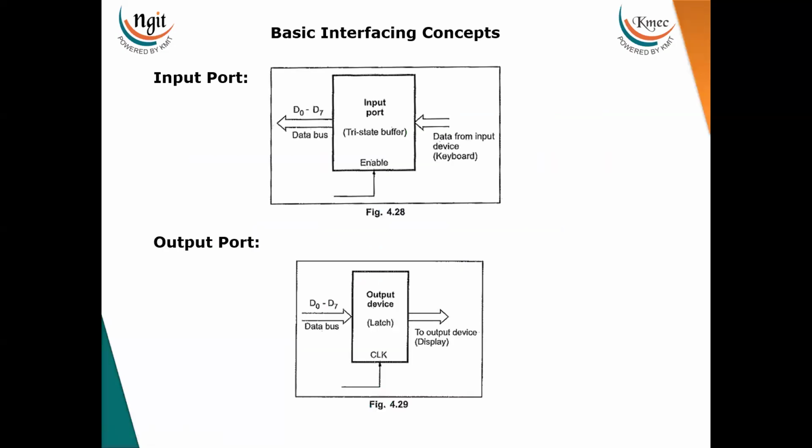In this lecture, we will study the basic interfacing concepts. Any application of a microprocessor-based system requires data transfer from the external device to the microprocessor and from the microprocessor to the external device. For that, we need an input port and an output port. Now, what is a port? The point or node where the I/O devices are connected to the interface is called